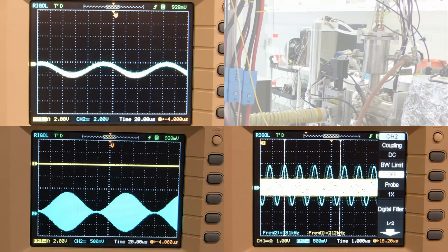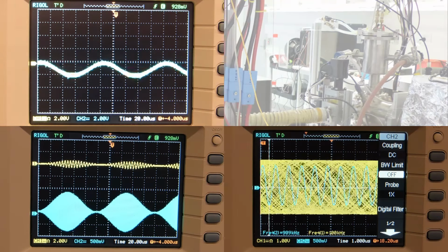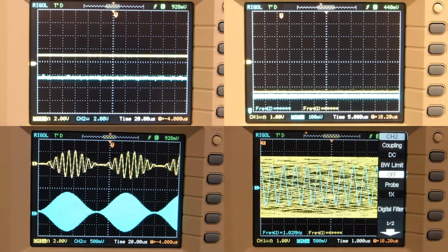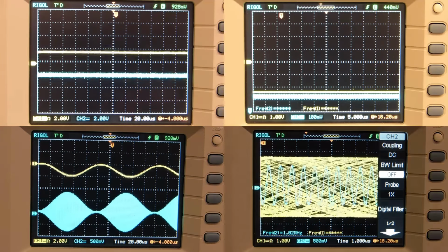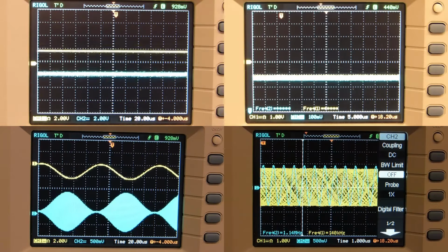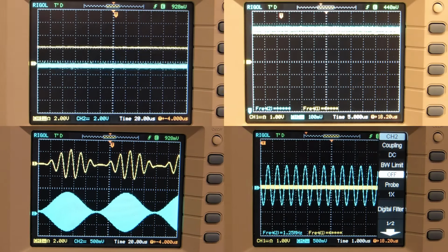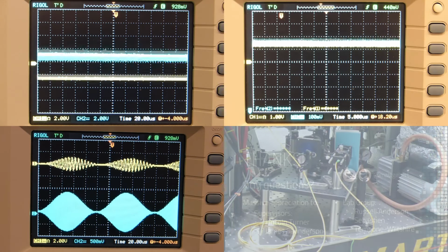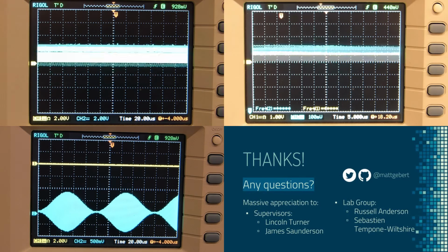On the bottom left, we show an amplitude modulated carrier signal. As we increase the frequency of the carrier, it begins to mix with the internal oscillator at the correct frequency, and a signal appears that's AM demodulated. On the top left, we show this same thing, but with the I and Q channels. We also switch between an AM modulated signal and just a straight carrier signal in this example. In the top right, we show the operational ability of our differential amplifier. One of the signals is the single-ended output from the DAC, and the other one is the amplified signal.